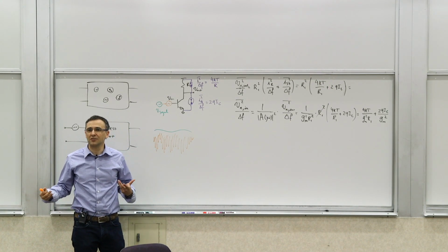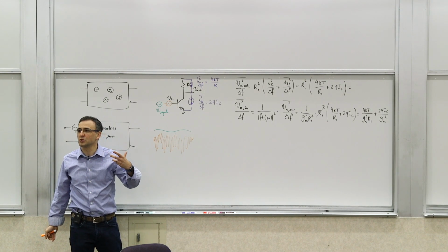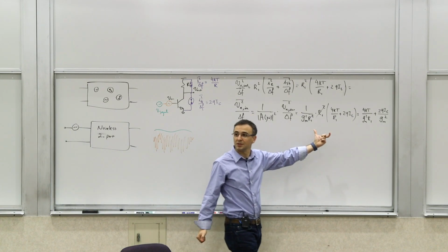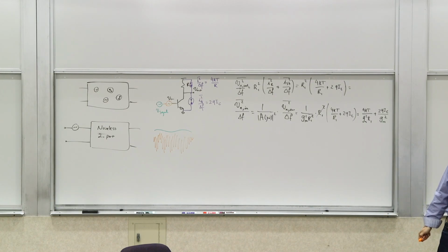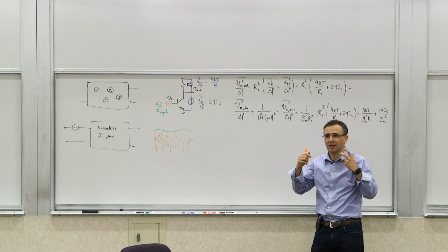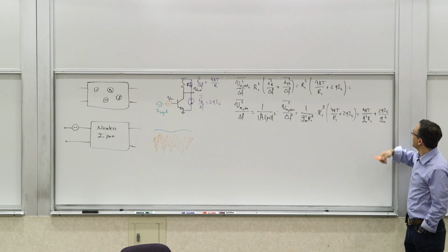So you get more signal power increase than noise power increase, so your signal to noise ratio improves, and that's reflected directly in the input referred noise. Input referred noise is another way of thinking about signal to noise ratios. So I'm talking about this from different angles to make sure it's very clear what we are trying to do. So, okay, that's what it is.